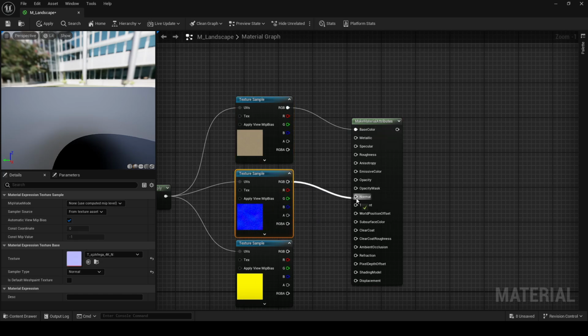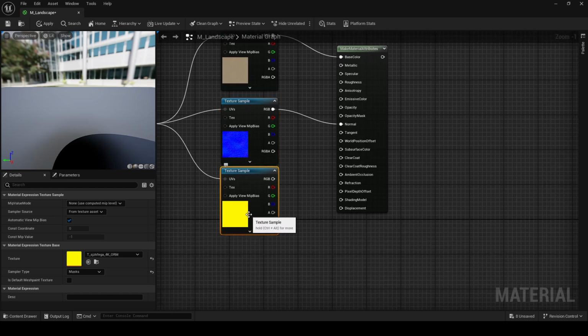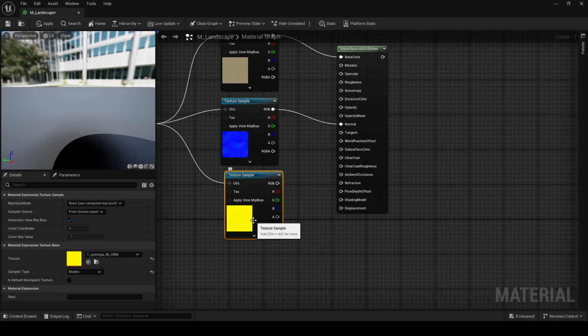And in this map we have 3 different maps within this texture. Just select this, and in the left side you can see the name at the end, ORM, means you can imagine this as RGB. We have 3 different options in our node RGB, so you can think according to that. ORM means occlusion, roughness and metalness. Okay, so we will connect this accordingly. So let's select our node and connect it accordingly.